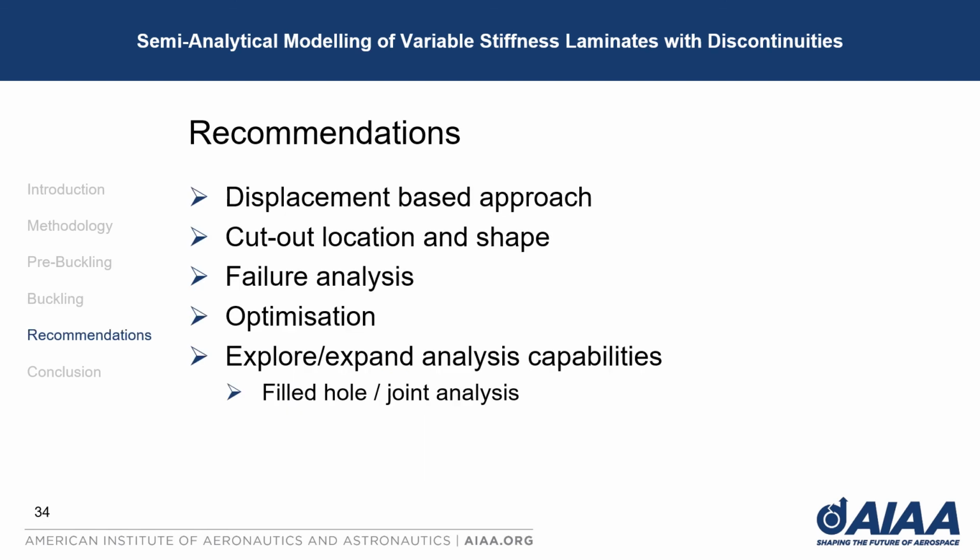So finally, some recommendations. First of all, the displacement-based approach has the great advantage of not needing the boundary conditions along the free edges of cutouts. It will be an improvement to the model to include displacement-based formulations for the pre-buckling analysis. Some more work could be done regarding different shapes and locations of cutouts or discontinuities, where in this work only central circular cutouts have been considered. The work so far does not include any failure analysis and does not include any optimization. And finally, it will be worthwhile to explore and expand the possibilities of this model, for instance, to use it in cases of filled holes or joint analyses.